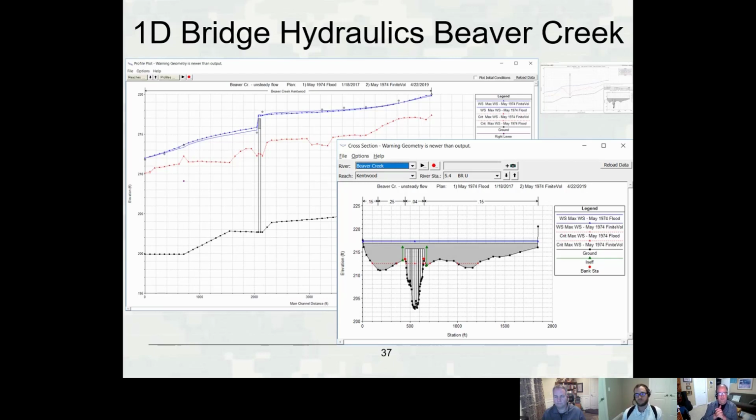Okay, I see the Preissmann slot being a very, very minor inconvenience, and the modified Puls, since you don't really need it with this technique, is not an inconvenience at all. So if you had models that were using modified Puls, just turn off the modified Puls and use the 1D finite volume everywhere.